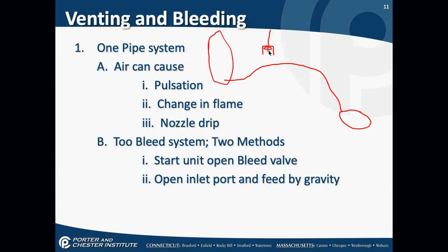You cannot use them on oil. They leak. It is actually illegal to use those type of fittings on the oil. The only thing we're allowed to use on oil lines is flare fittings. Now, a flare fitting, you take the end of the pipe and you use a flaring tool, and you create a sort of a cup-shaped end, and the nut fits over this, and because this is actually part of the pipe and it clamps down to another fitting, a brass fitting, it makes a very solid seal.